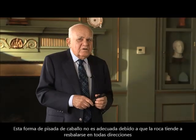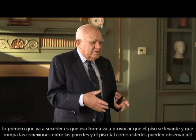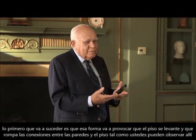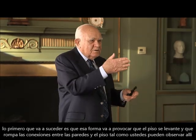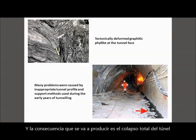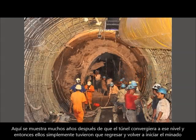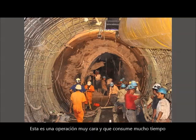A horseshoe is not a good shape because the rock tends to squeeze in all directions, and the first thing it will do is pop the floor up and break the connection between the walls and the floor, as you see there, and ultimately that leads to almost a complete collapse of the tunnel. This is many years after the tunnel had converged to this level, and they simply go back and remine it. But that's a very expensive and very time-consuming operation.